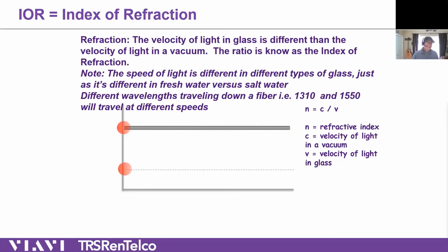And because of this principle we call index of refraction, in other words, the speed of light, we can tell with fairly good accuracy how long that fiber is. And we can also tell you where your events are in that fiber. Again, your breaks, your bends, your splices, your connectors, all of that is done based on this principle right here. Again, if you like to Google stuff, index of refraction in an OTDR will really bore you with the definition, but this is effectively what it is.